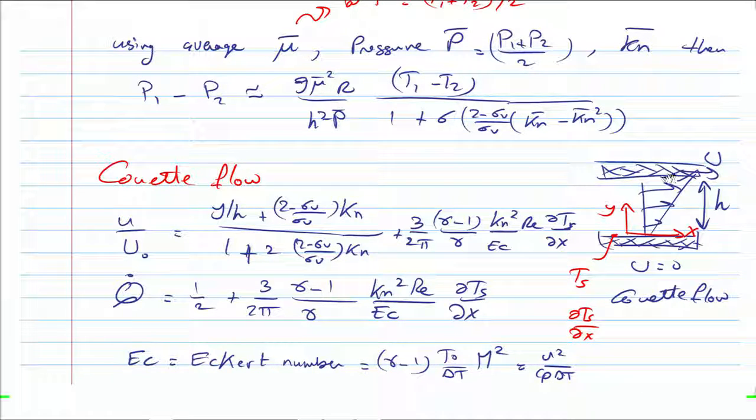So why am I expecting it to decrease? Because I'm thinking, well, if the velocity is like this for no slab, with slab it would be like this, right? It would be only this much. But what happened at the lower wall? It will also be more. So the reduction from the upper wall gets balanced by the increase in the lower wall. At the end of the day, with or without slab, you end up with exactly the same flow rate, right?